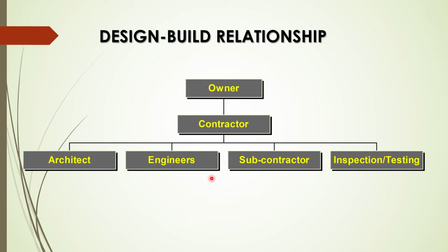Typically in the previous relationships, the contractor's not even involved until after the design is done. So in this relationship, the design build, hence design build, the design is being built at the same time, so there can be changes back and forth. Okay, and there's liability in between the two, whereas before the design would be completely done, it would be put on the shelf, and then it goes out to bid, and then the relationships happen.